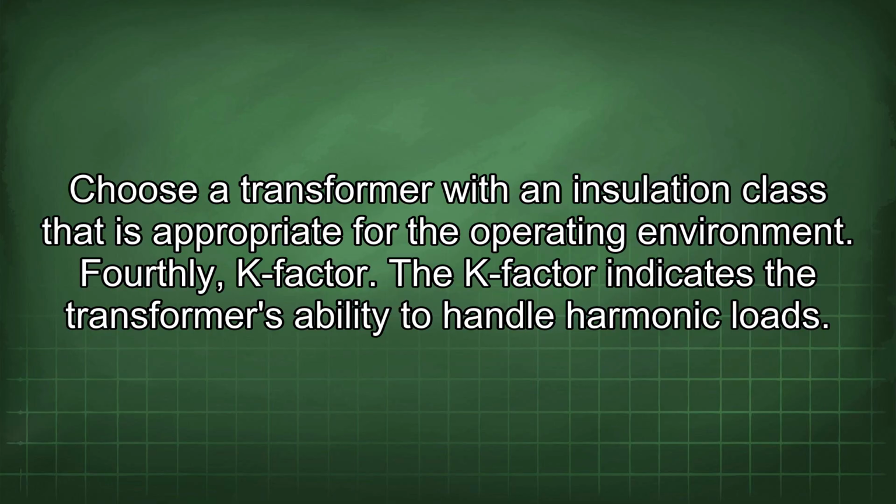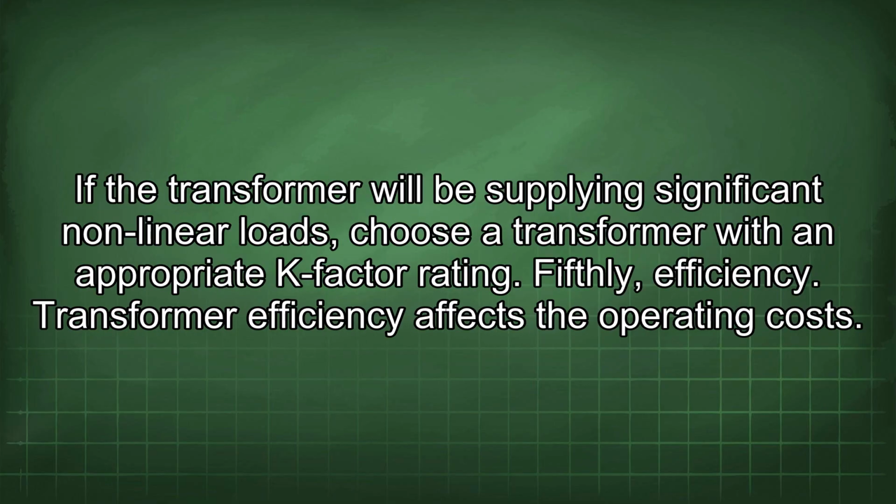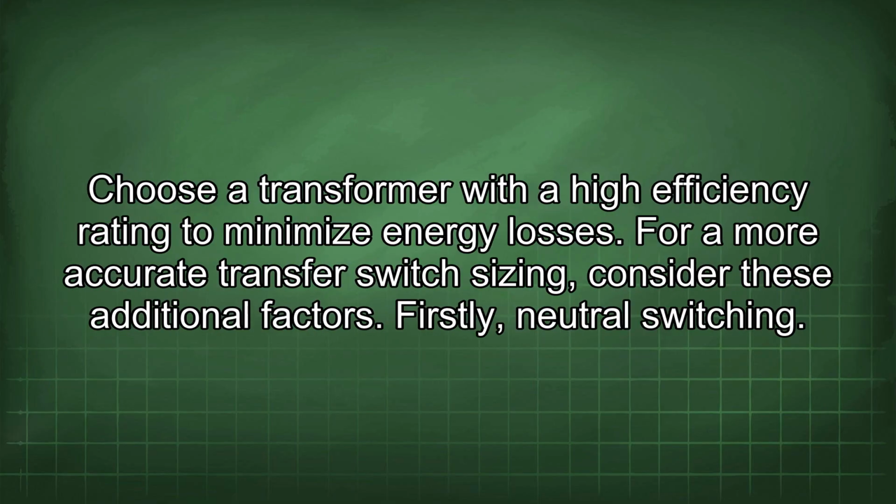Fourthly, K-factor. The K-factor indicates the transformer's ability to handle harmonic loads. If the transformer will be supplying significant nonlinear loads, choose a transformer with an appropriate K-factor rating. Fifthly, efficiency. Transformer efficiency affects the operating cost. Choose a transformer with a high efficiency rating to minimize energy losses.